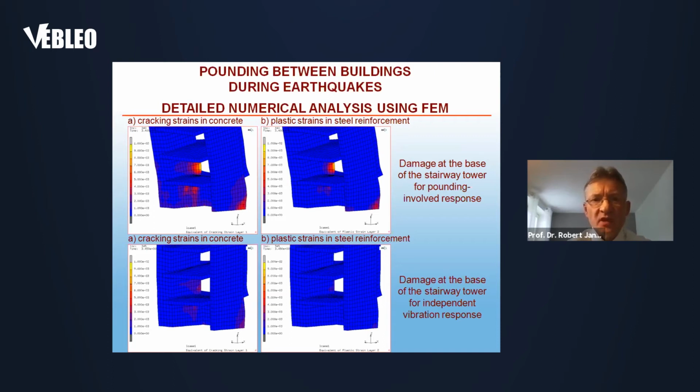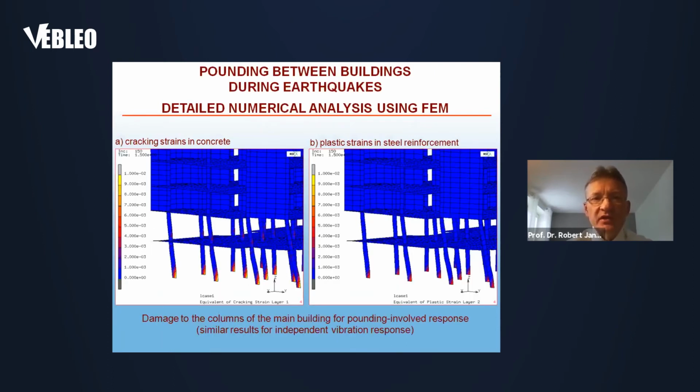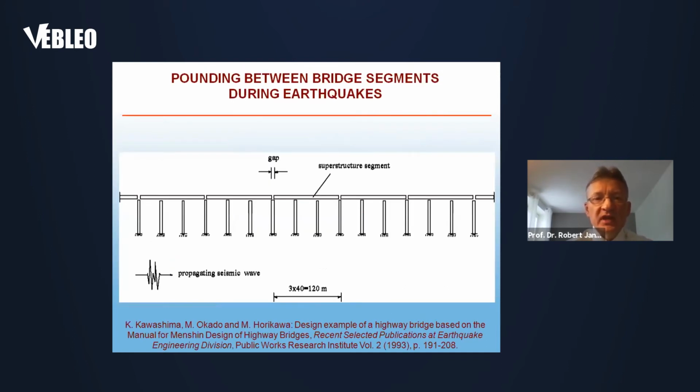On the other hand, when we look at the response of the much stiffer main building of the Olive View Hospital, cracking strains in concrete and plastic strains in steel reinforcement are more or less on the same level for both pounding involved as well as for the independent vibration responses. Let me now move to pounding between superstructure segments in elevated bridges.